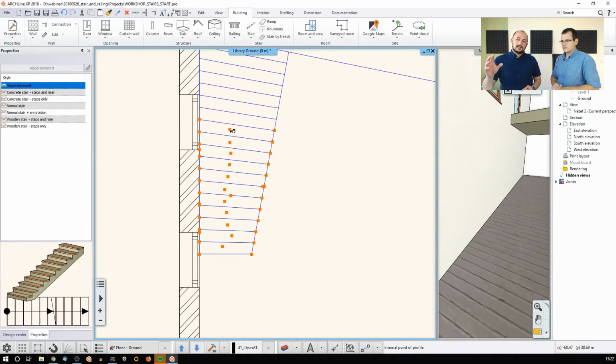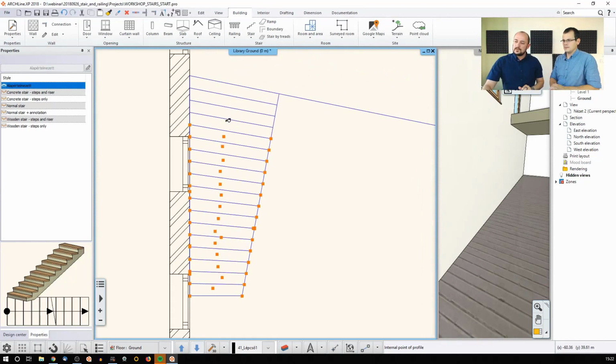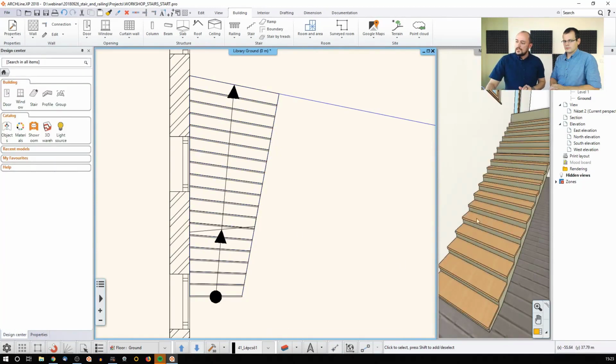Now, there is a mistake that you can make here, and it's if you double click inside one step. The software is recognizing the shapes and adding them one by one after each other. But if you double click into one, then the software will go and go and go and go, and this will result in a very weird stair shape. So just take care about that. Other than that, you just need to click and find the shapes, and this is all. I just hit enter, and because I do not want to select another option from the right-hand side, I tell it I'm finished with another enter, and then the software creates this staircase.